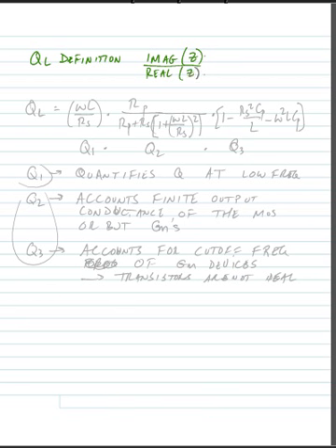In other words, we're looking at the energy storage capacity of the circuit, the imaginary portion, divided by the energy dissipation portion of the circuit, the real portion of the impedance. In other words, reactance over resistance. Now this isn't a very accurate definition for quality factor once we pass the self-resonant frequency, especially for passive circuits, but it will work below the self-resonant frequency of the circuit.